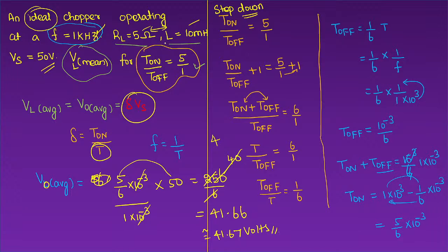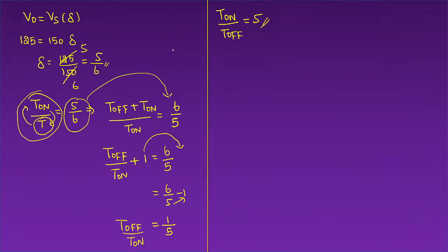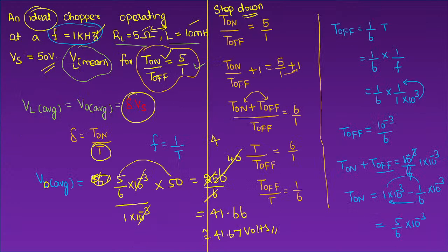Because they haven't given any other data in the question, only the on to off time ratio. So if any other circuit is given, it will be mentioned. Like in the last other two cases, they gave the clue to identify what type of circuit it is. But in this case, if they have given only a general chopper circuit, it will behave as a step down chopper only. Very first we designed a general chopper circuit. So here they have given general data.